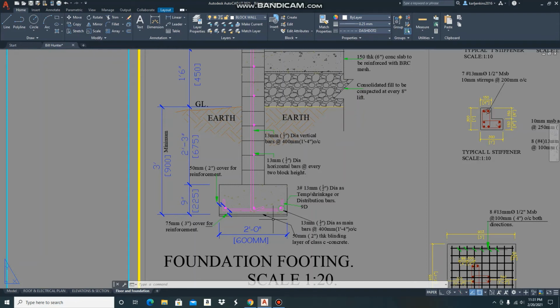And remember, as I said before, your footing is supposed to receive the gravity loads, meaning your dead load plus your live load plus the self weight of the building must transmit down to your wall and to your footing. And what the footing does is spread that load evenly across the foundation. So the wider your footing, the more stable the structure.